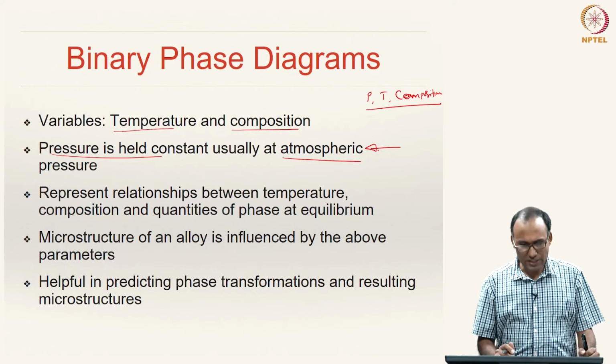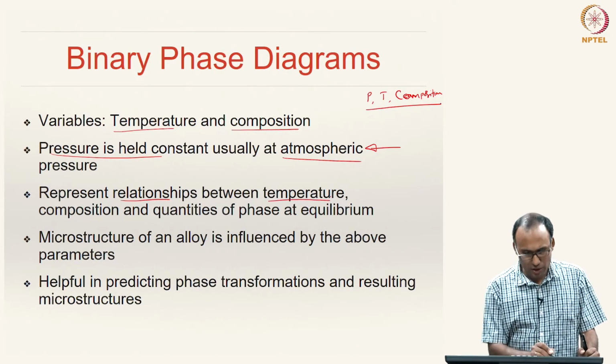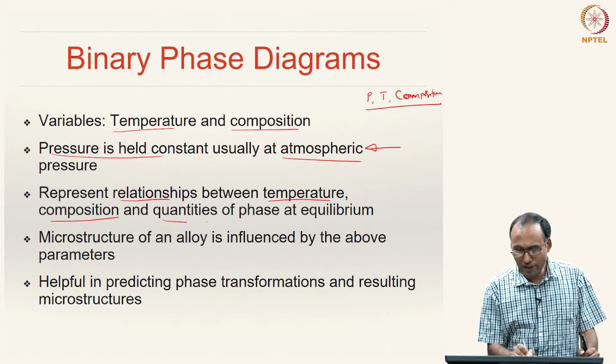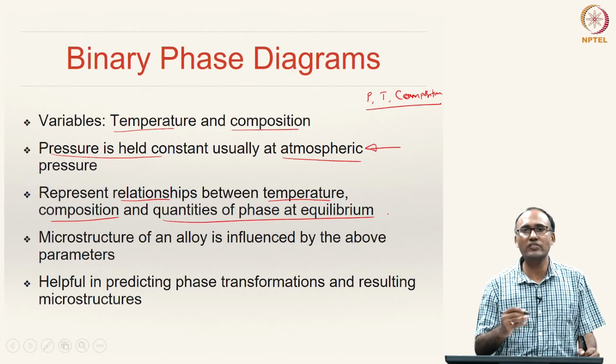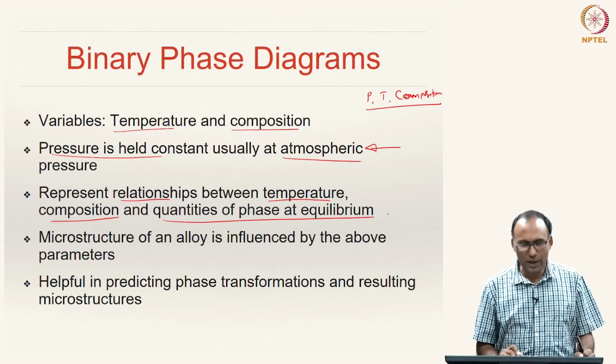So, the binary phase diagrams represent the relationships between the temperature, composition and quantities of phases at equilibrium. What are the different phases and what are their quantities? This is something that will be clearly described by a binary phase diagram.